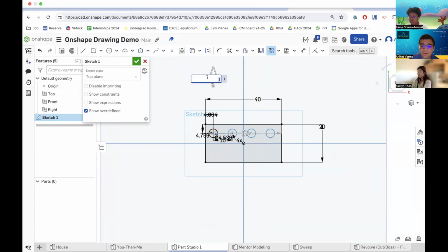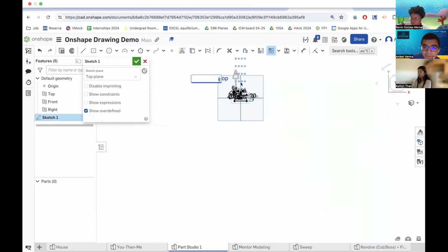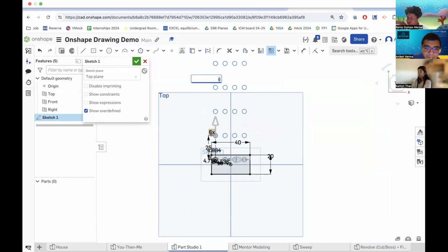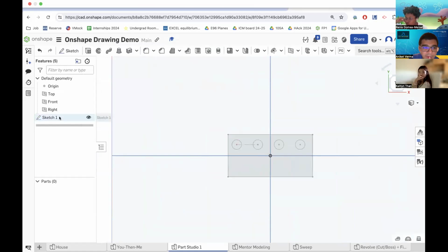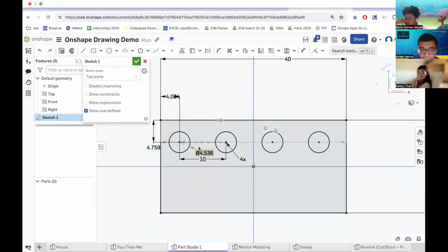So the same thing goes for the y direction. If I change the number of instances, then I'll have the option to change the distance in between them and whatnot. That just helps you multiply this with respect to the original sketch. So if I go back to my 4 dots here and hit OK on the sketch, and go back into it, you'll see that all of them have a black outline, which means they're all fully defined, because they've all been done with respect to this one.